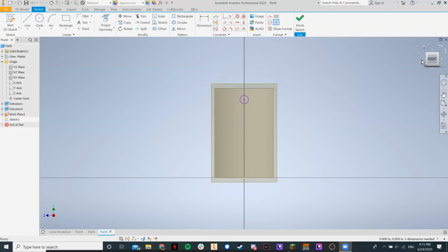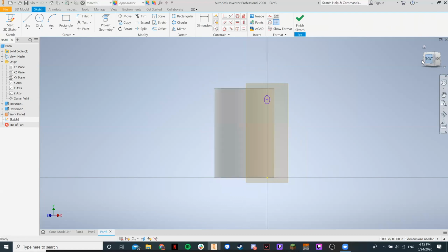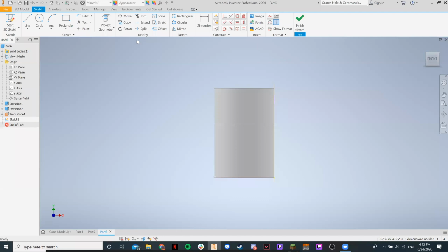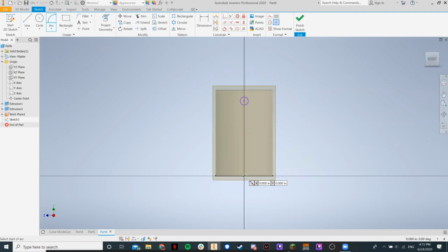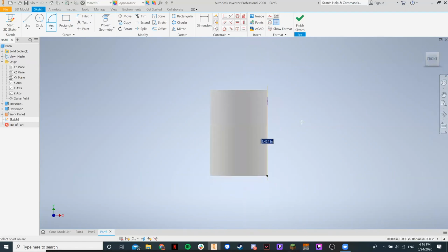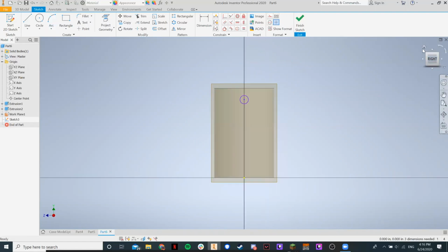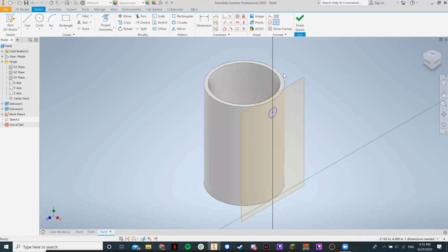So let's go ahead and change the orientation of our view. And our mug handle is gonna be an arc, right? So let's go ahead and click arc and hover over this. Hover over the center of the circle until it turns green, and let's drag it out this way. And now since this is coming our way, right, we don't want it curved like that. Now here, wait, hold up. Oh, right. I forgot to change the plane, that's my bad.